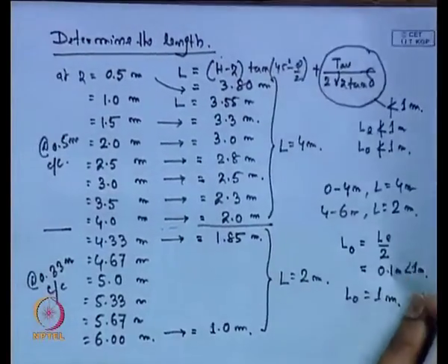So, next category is the design of the reinforced retaining wall. In the other designs of retaining walls, when you are talking about the cantilever retaining wall or gravity retaining wall, basically we consider various factors of safety, that means factor of safety for sliding, factor of safety for overturning, factor of safety for bearing, and no tension zone.